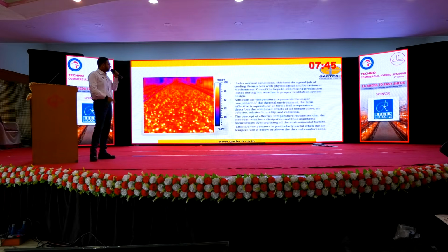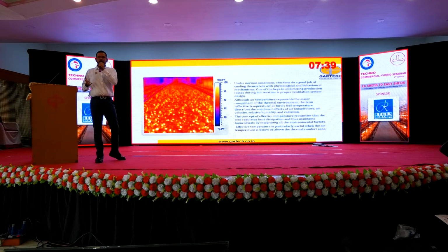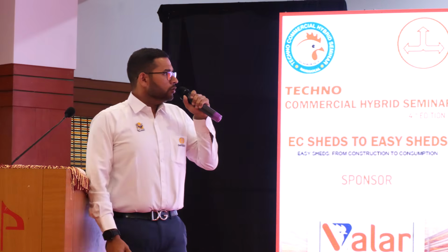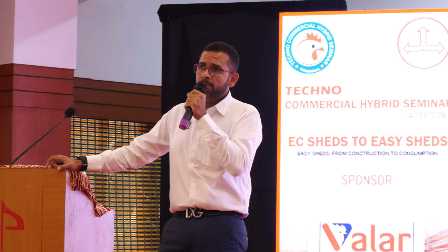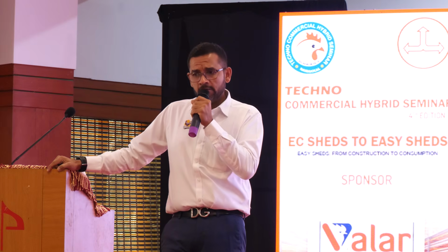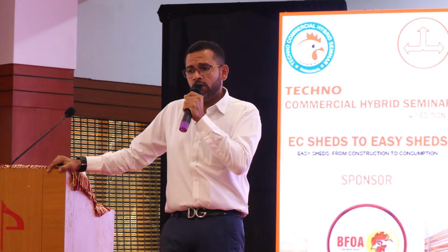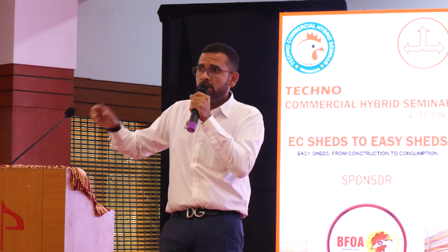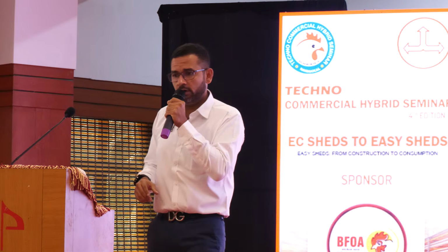As I said, under normal conditions it is not a problem, but in our country, in India, we don't get normal conditions for 8 months out of 12. No matter where you go, we always have this issue. So I totally agree that air temperature is going to represent a big part, but again, because we are not using air conditioning and we are using evaporative cooling, the humidity has to be considered when we do any kind of heat loss that we have to achieve inside a poultry house.